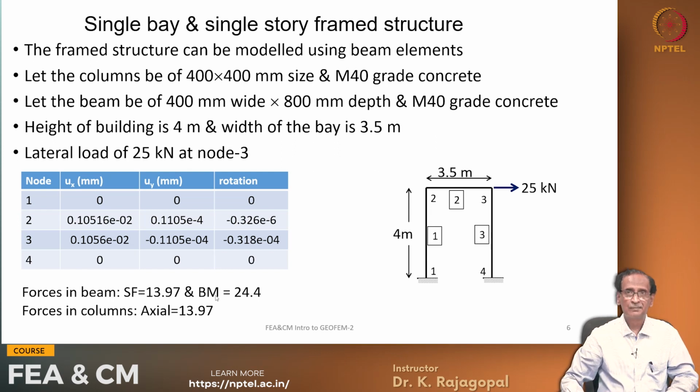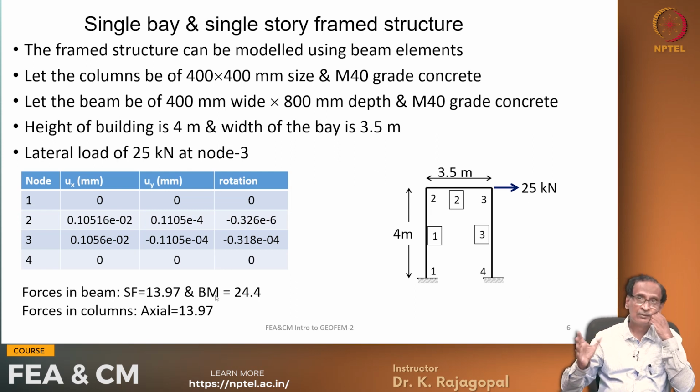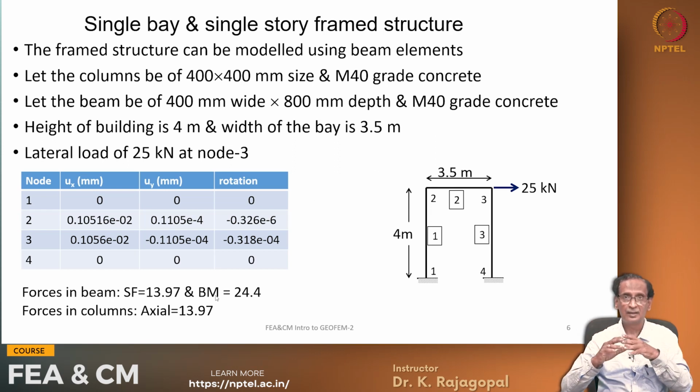And what happens when one of your supports undergoes some relative settlement? Previously, when we applied some settlements for our truss structure, the settlements had no effect on the element forces, because all the joints are hinged connections, so the structure can freely rotate and accommodate the deformations without increasing the forces.